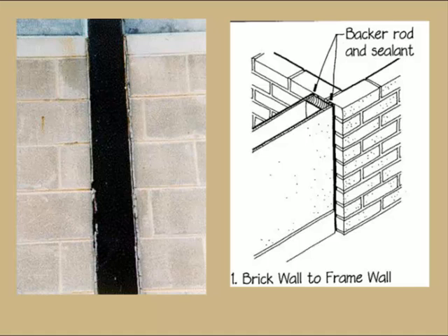Proper materials used as the backers for these is important to make sure that you get the correct depth and profile of the sealants. And you're looking for a 1-to-2 ratio of the depth to width on these, and a 2-point adhesion for the sealant to get proper movement out of the seal. Okay.